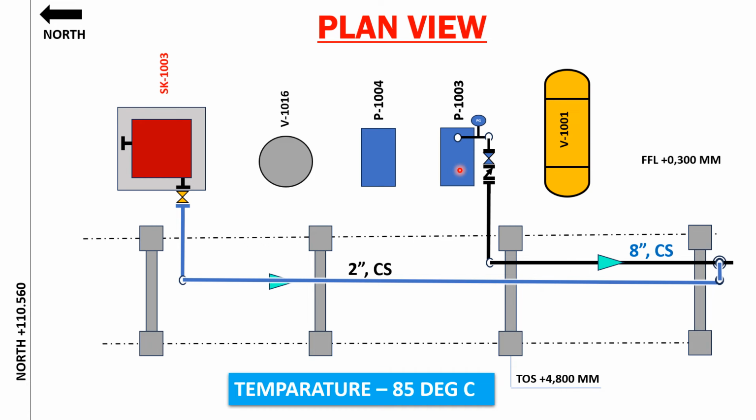Okay, so let's get into the subject. This is our final layout. Let's analyze the layout first. From here the line starts. You have to imagine that the line is at 85 degrees Celsius. Let me take my pen actually. At 85 degrees Celsius, the equipment point is fixed. So this point is not going to move.